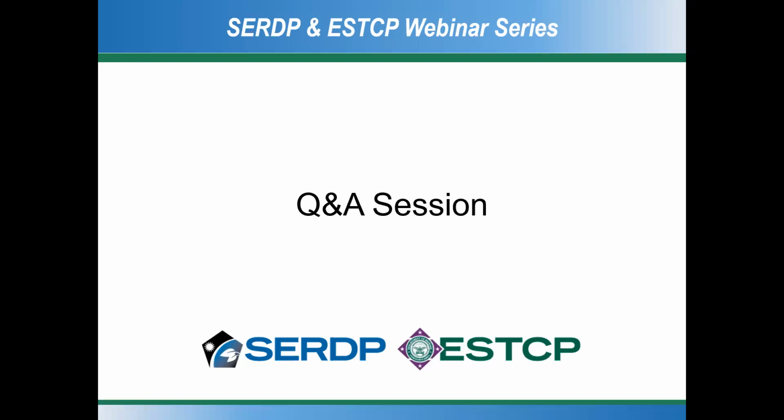Wonderful. And this next question is from Jacobs. Have you conducted any tests to verify the integrity of the grout seals? Yeah, that's a good question. During some of the slug testing, both the falling head and pneumatic slug testing, we did have transducers in adjacent screens and did not see any hydraulic influence whatsoever. And of course, we've got a lot of chemical variability preserved, so we don't think we've got failure of the seals at all.